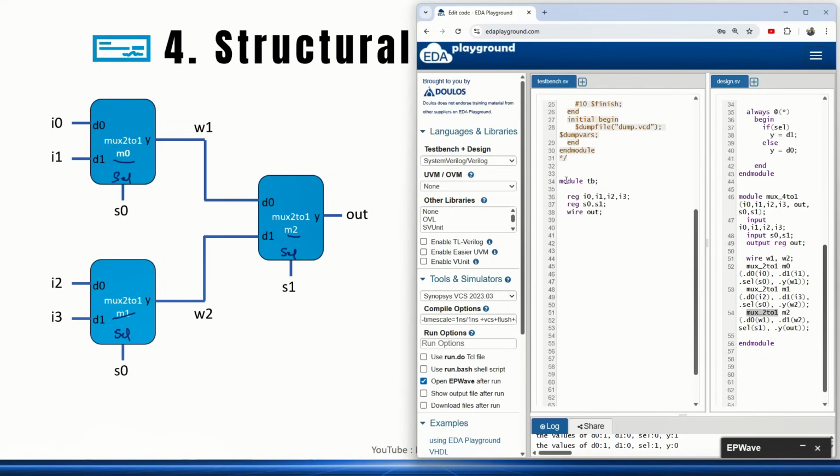And then after that I need to instantiate the multiplexer mux 4 to 1. So here we can instantiate this as per the order we have followed here. That works actually. You can see Control C. Here I am going to use something like M1 as my instance, or let me write it as DUT itself, and then I can have the connections like this. This is the order I am following. I0, I1, I2, I3, S0, S1 and out are the signals we have declared here. So in the same order we can put it here like this. Then these will be directly mapped.